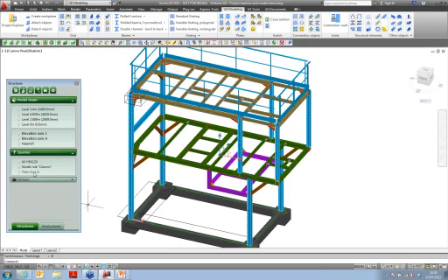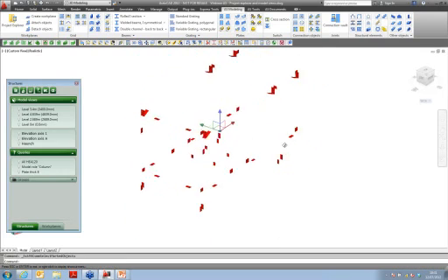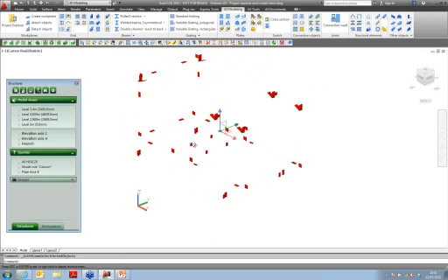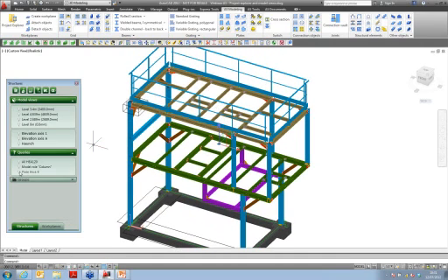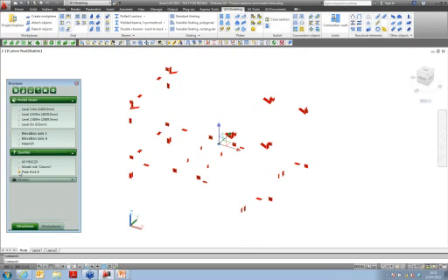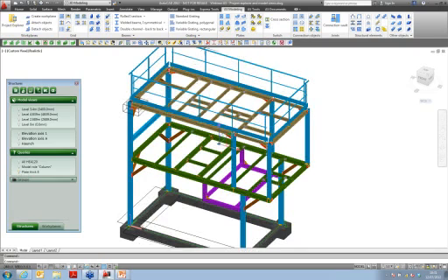appears here, and if I want to run it, I just select it and with a right click say I want to execute it, and now all my plates which have a thickness of 8 are in red color. I can select them, and I can also very easily see them in my model. So if you just click this button, you see directly all the plates which correspond to this query. Okay, let's remove the red color.